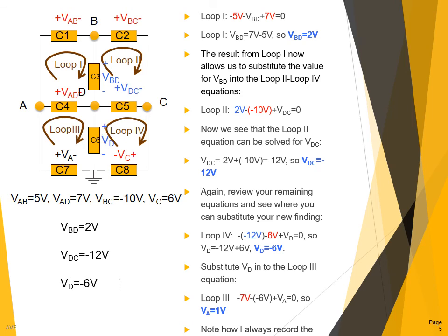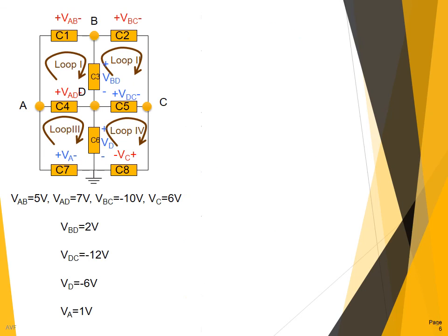Okay, so take the time now to write your results in there. And you see that as I was writing the results, the voltages on my circuit, I changed them from black to blue. And I look at my circuit and I see now that I have, in fact, solved for the remainder of the voltages in the circuit. How do I check my work? Well, I go through loop 1 again and I substitute the known voltages.